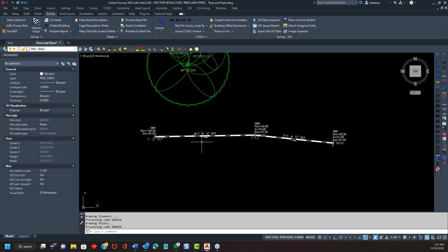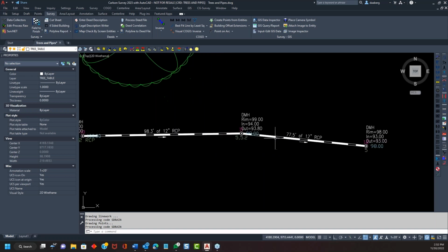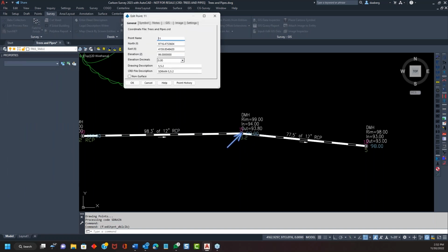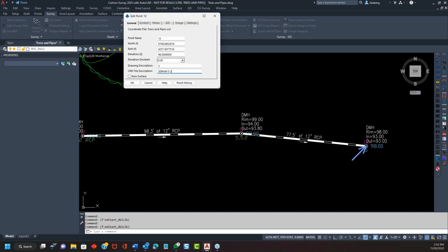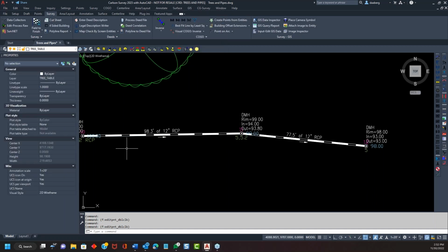So what if this pipe size changes? Well, it's a very similar approach. Again, this section is separated by commas without spaces, so you don't want to put a space in there. Now we have a pipe size. So there's a 12-inch coming in, and let's say there's a 24 going out. Then we have to tell this one, since we've done that, that there's a 24 coming into it. So this section is 12 and this section's 24. I process that and I get the pipes drawn at the widths that they are.